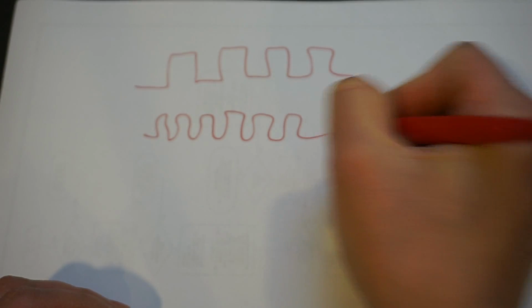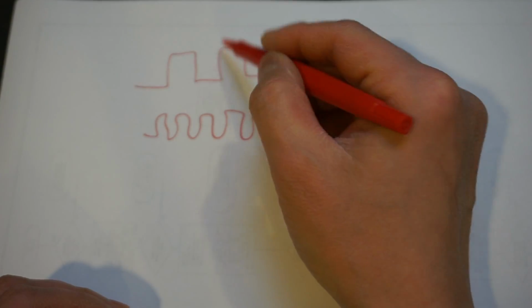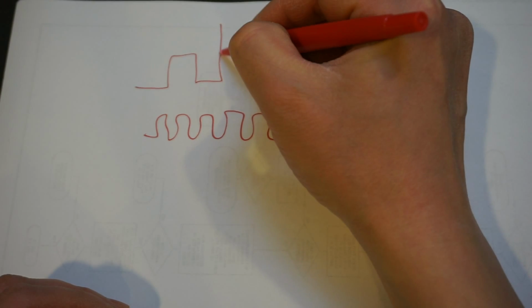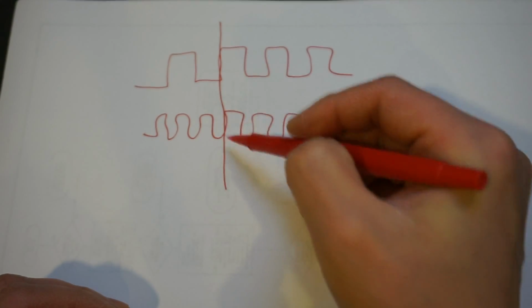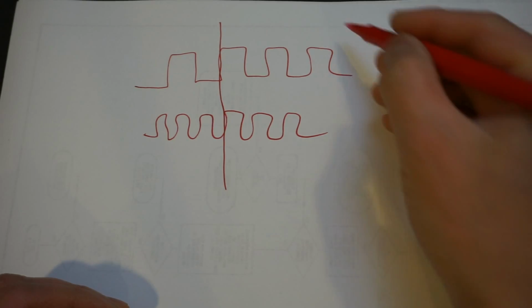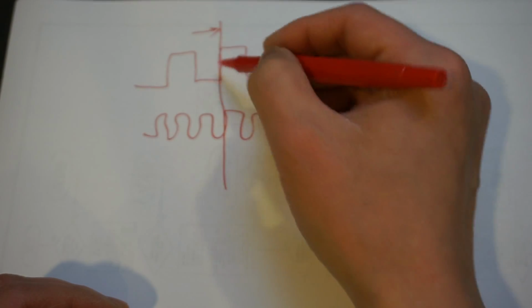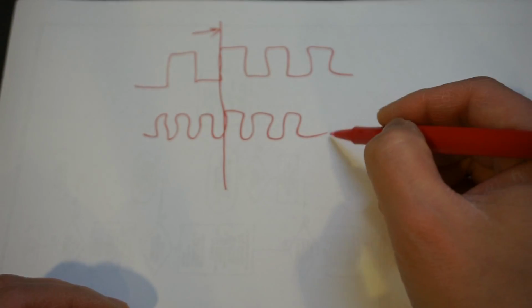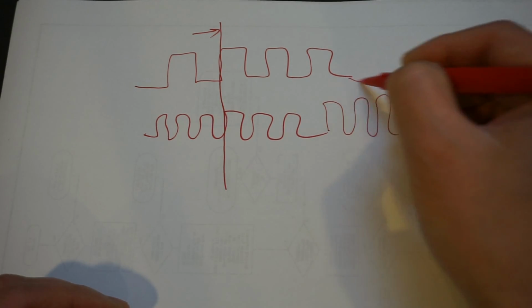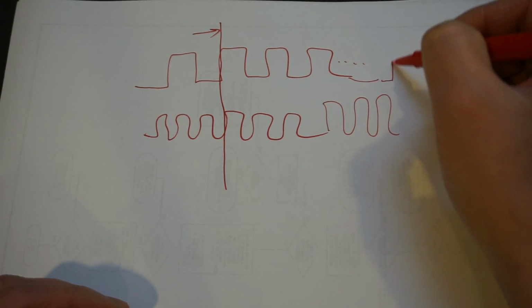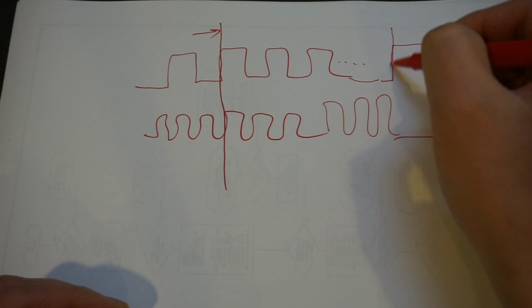Well, so again, we have our signal coming in, and we have our free running clock, right? So the idea is, at a certain point, we can find a trigger that the clock's rising edge matches our signal's rising edge. And so let's say we use this to start counting. Using our reciprocal counting method, we can start counting when these 2 edges align. And then we let the counter run for a while till the time comes that, let's say the start and,